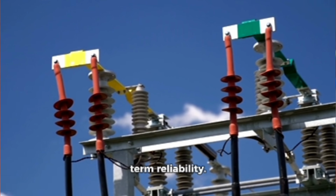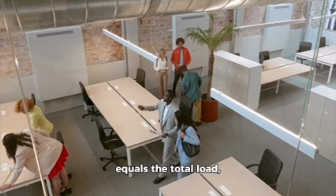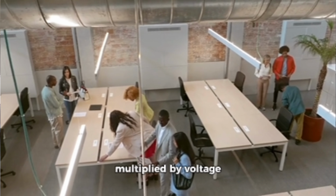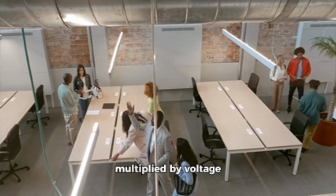For this office design, the total load is 57 kilowatts, and using the same formula for current calculation, current equals the total load divided by the square root of 3 multiplied by voltage and power factor. With 400 volts and a power factor of 0.8, the current comes out to 82.3 amps.